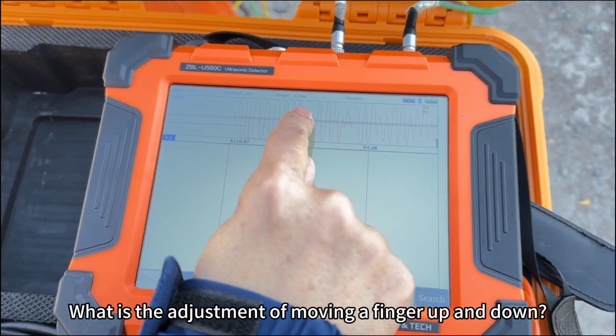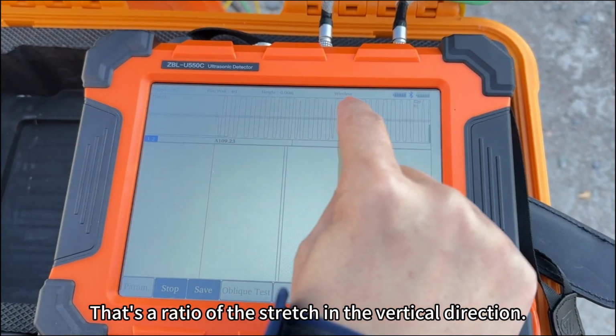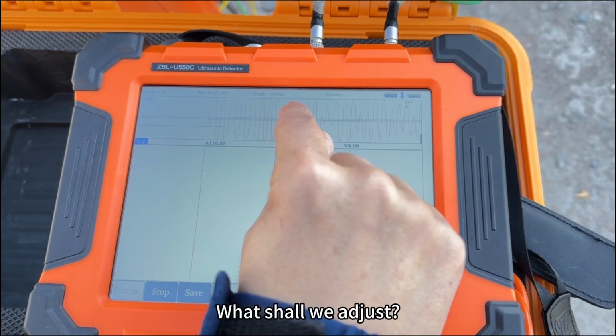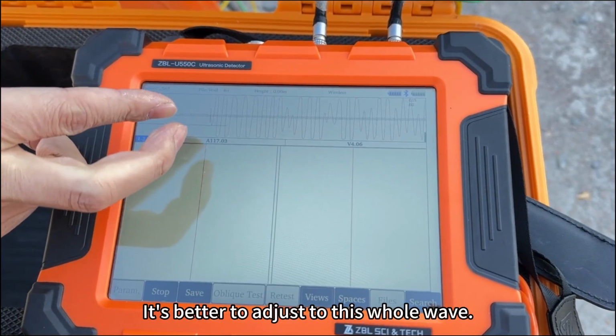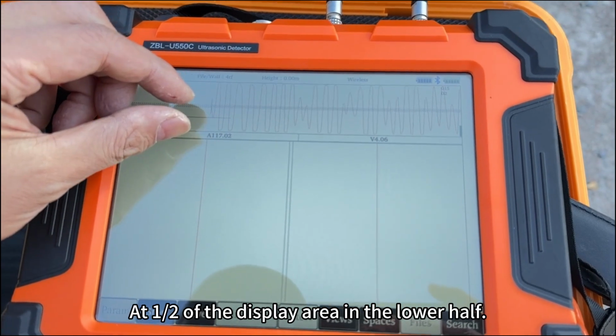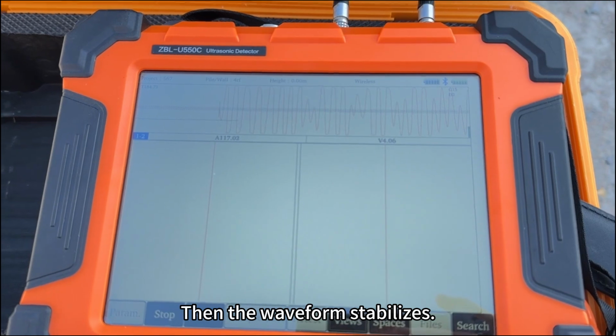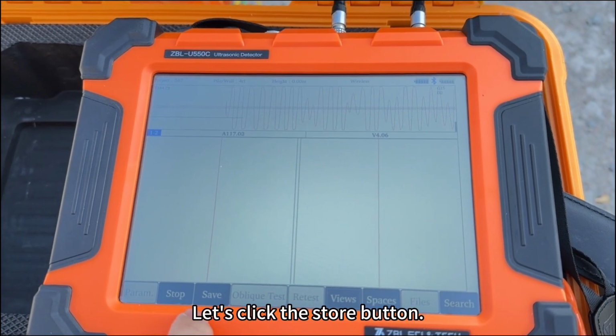Moving a finger up and down adjusts the gain of this wave. That's a ratio of the stretch in the vertical direction. It's better to adjust this whole wave to 1/3 of the display area in the lower half. Then the waveform stabilizes. Let's click the Stop button.